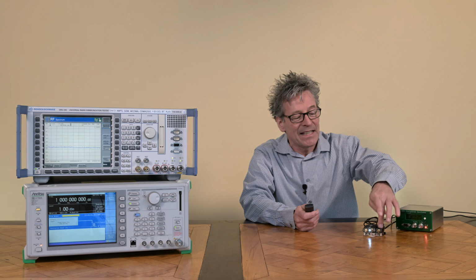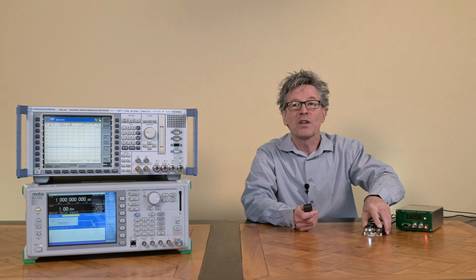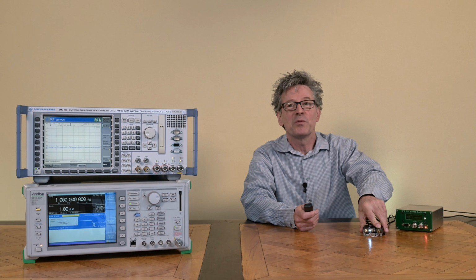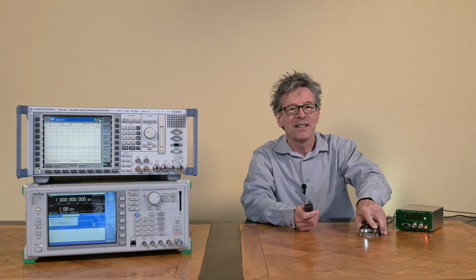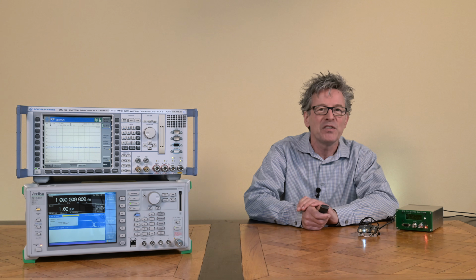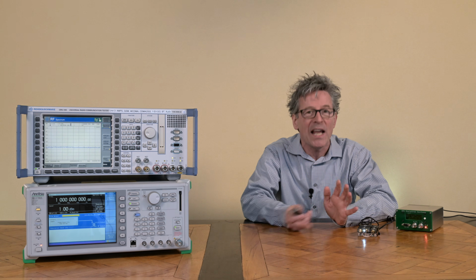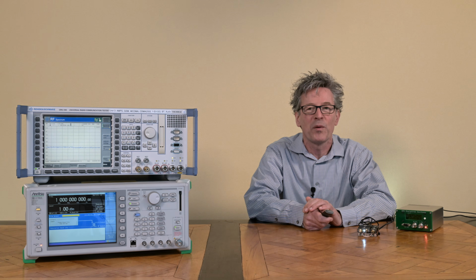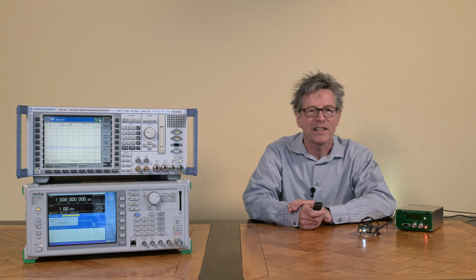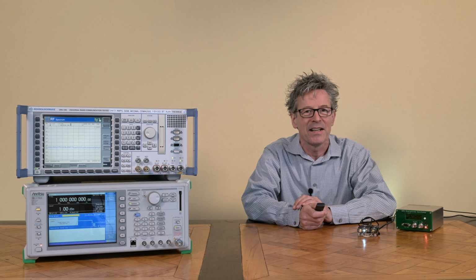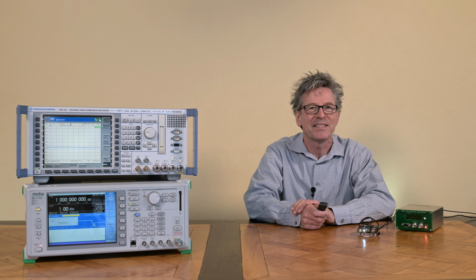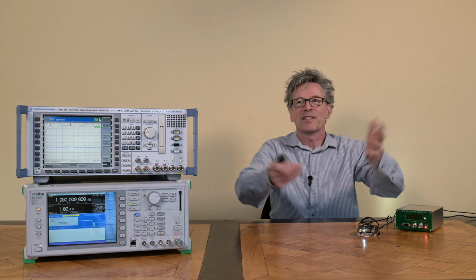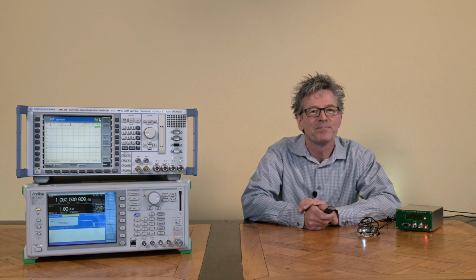And adding then a low pass filter only for 10 megahertz, in case you want to use it for this type of timing things, etc. I think then you're basically perfectly fine. So I like this kind of combination, and I think it comes from the fact that this is a flexible device rather than being a limitation, in a way. But well, it's up to you what you think about it.